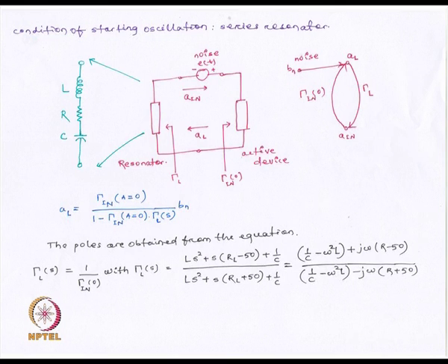Of course, here you have to first start the oscillation. So, suppose you assume this resonator to be a simple series RLC network. Then gamma L will be given like this. If you take a simple Laplace transform of the input impedance, this expression for the reflection coefficient is obtained from ZL, which can be simply calculated.